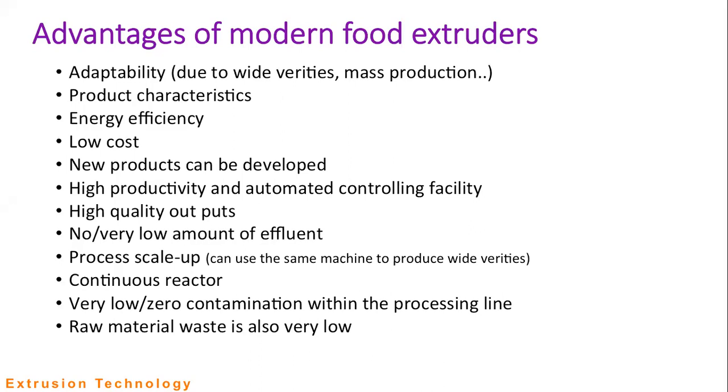And different product characteristics we can get by altering the extruder parameters, maybe pressure and the barrel temperature and barrel speed. So we can control these things.